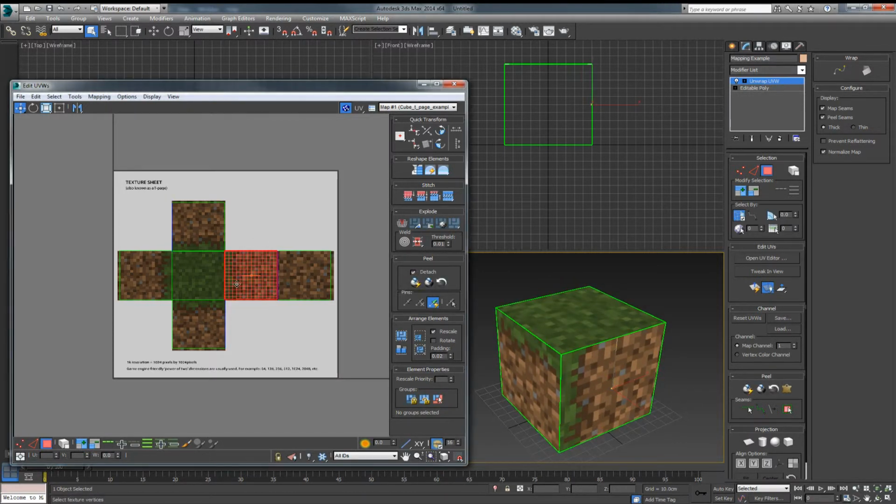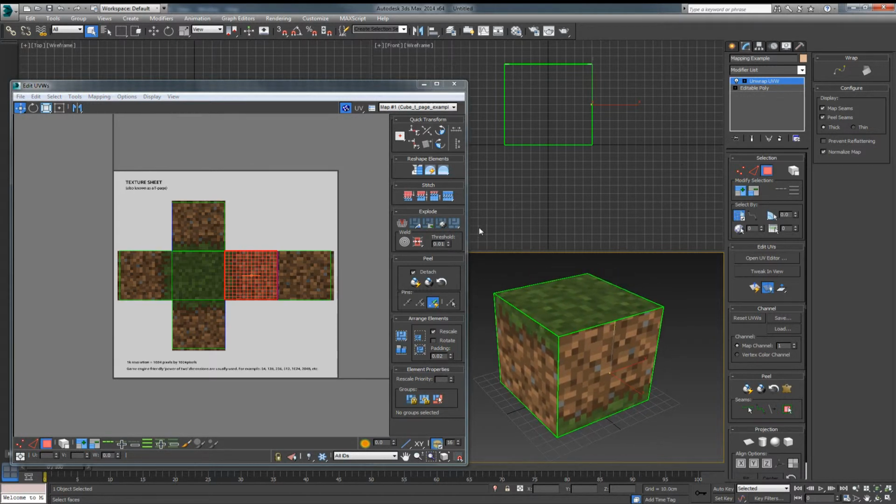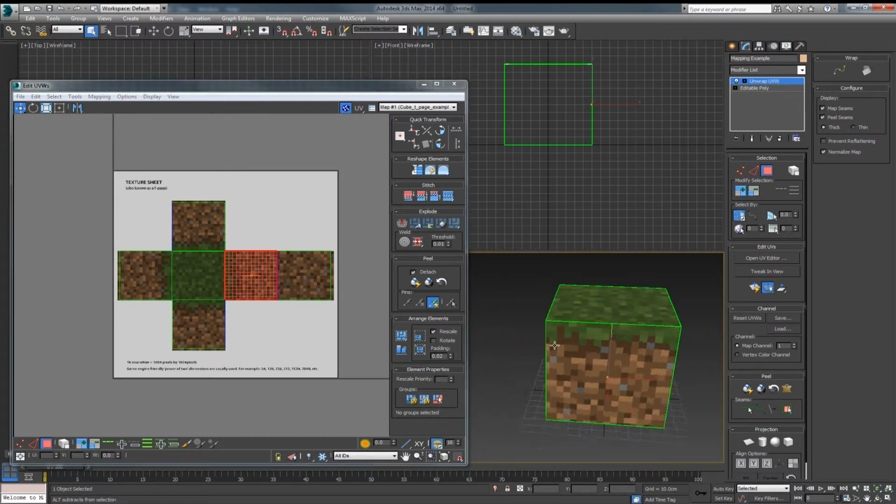But this one, for example, which happens to be this one here, needs to be rotated 90 degrees. I have the facility over here in this viewport to rotate 90 degrees. Click on it once. Doesn't appear to be any change here. Of course, if it's spinning from the middle 90 degrees, you wouldn't really register any movement. Over here, nothing seems to have happened, but the viewport just hasn't been refreshed. If I just middle click and drag, you can see that it updates the viewport, and I can see the effect of what I've just done over here. Let's click again, and one more time. It shuffles it round, and now that's correct.